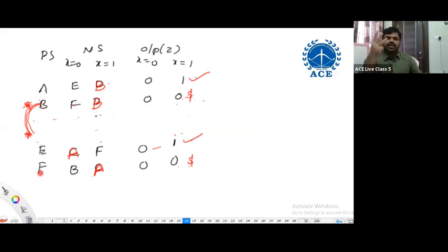As I mentioned, the 3 rules are very useful. You apply them and you can eliminate extra or redundant states. The remaining states are the actual states, and whichever states are eliminated are redundant. They may ask how many states are redundant or how many states remain after minimization, by giving a state table or a state diagram. How many states are there after minimization? 4 states. How many states are redundant? 2 states.